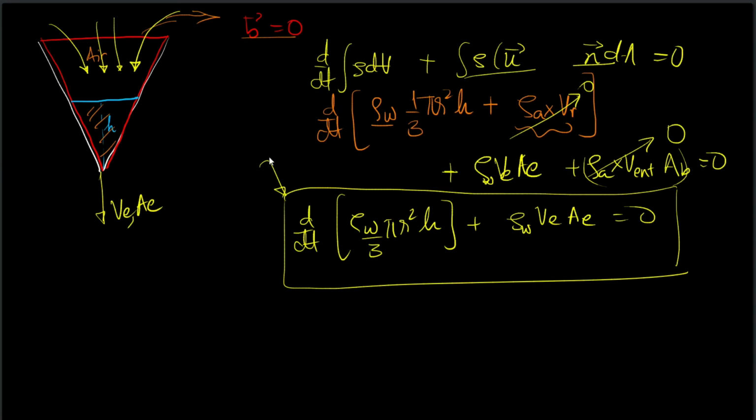So this is a combined control volume with air and water, and the fact that air has quite a low density compared to water causes all those contributions to the conservation of mass to vanish. But ideally you can do a conservation of mass for the air control volume and for the water control volume separately. So the air control volume will be moving with this velocity downwards, and the water control volume will be moving downwards. So you can essentially repeat the above problem for air.